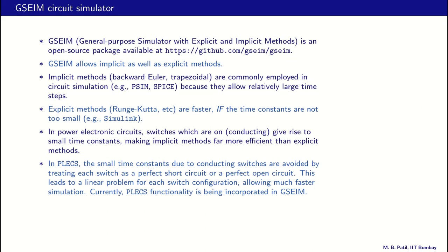There is one different approach that is used in the simulator called Plex, and what they do is they avoid the small time constants which arise because of conducting switches, and they do that by treating each switch as a perfect short circuit or a perfect open circuit, and this leads to a linear problem for each switch configuration, and that allows much faster simulation, because each linear problem basically means you have to solve Ax = B, and you can just compute A inverse once for a particular switch configuration, and you don't need to repeat that calculation again, and therefore this kind of approach is much faster.